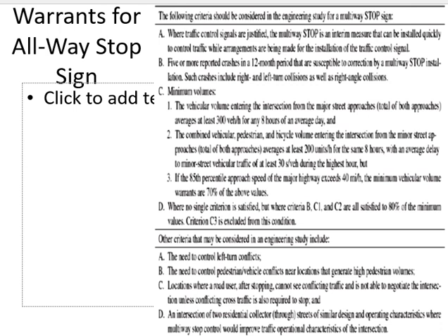So let me try to summarize. You decided that in the near future on this intersection you are going to put a signal. What should I put right now? You can go for an all-way stop sign temporarily. If this is not the case, then you look at the number of accidents you have. If you exceed this value, put an all-way stop sign. If this is also not satisfied, then you look for these two conditions, 1 and 2.